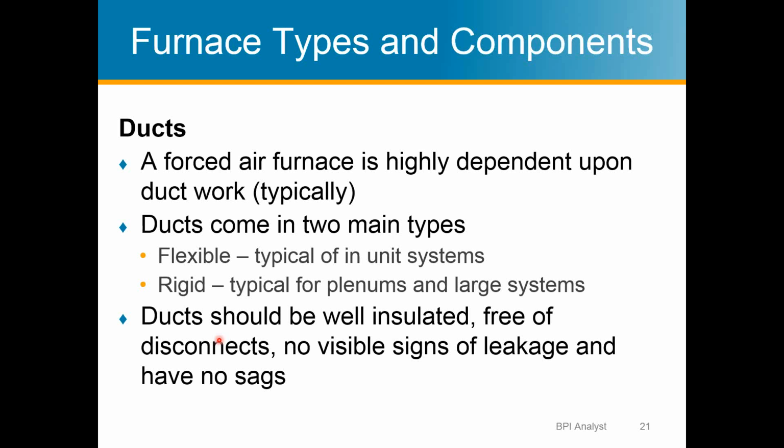And typically, the default duct leakage rate in California is about 30%. I've certainly seen duct systems that are leaking 90% or more, just disconnected ducts where they've completely come detached. Somebody was in the attic putting away their Christmas ornaments and stepped on the duct and it fell off or something. So that certainly happens out there. So just don't forget the ducts. It's not all about the expensive, shiny equipment.